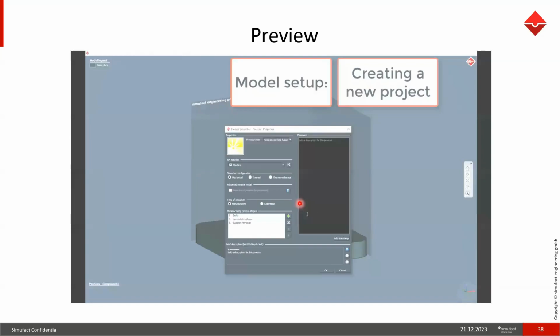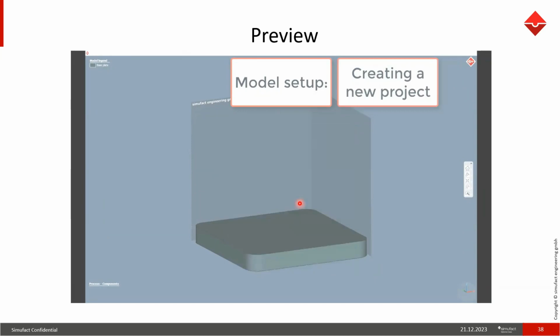So you can get your CAD model or the STL file inside the project like this. We get templates for each machine. Like if you are using an EOS machine, you will get a ready-made template for your base plate, for the EOS machine dimensions and particular thickness, so that you don't have to make it manually. You can just pull out your machine from the window. You can use the same machine parameters that they are using in the EOS manufacturing process.